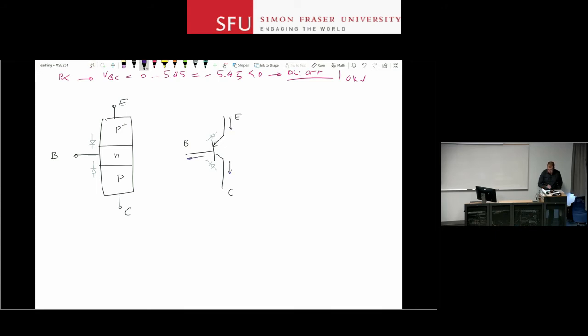Now, one difference between the two transistors is the direction of currents. For an NPN, the directions are the opposite. So IE goes in while IC and IB come out of those terminals. And again, that's because of how we use this. A PNP is closer to the power supply, the positive supply, and therefore the current from the collector usually goes into something else at the bottom, and this convention makes my life a bit easier.